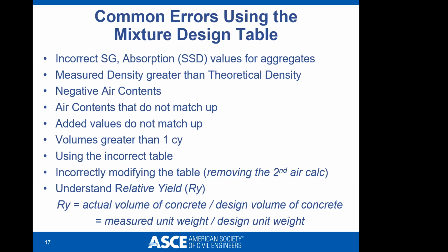Also, while it's fairly easy with the ASTM standards to determine absorption values for, say, a shale or sand, it is difficult for the cenospheres and the microspheres. It's problematic because most of that stuff generally tends to float. Also, the standards usually are for 24 hours of soaking. In some aggregates, you're required to do it for 72 hours. So you may want to look up some information on the web, textbooks, or from the manufacturers to figure out whether or not you have the correct absorption values for your aggregates.